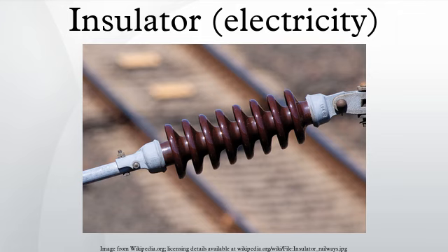Standard disc insulator units are 25 cm in diameter and 15 cm long, can support a load of 80 to 120 kN, have a dry flashover voltage of about 72 kV, and are rated at an operating voltage of 10 to 12 kV. However, the flashover voltage of a string is less than the sum of its component discs, because the electric field is not distributed evenly across the string but is strongest at the disc nearest to the conductor, which flashes over first. Metal grading rings are sometimes added around the disc at the high voltage end, to reduce the electric field across that disc and improve flashover voltage.